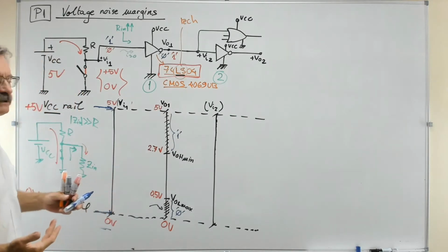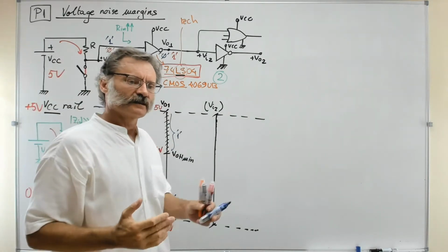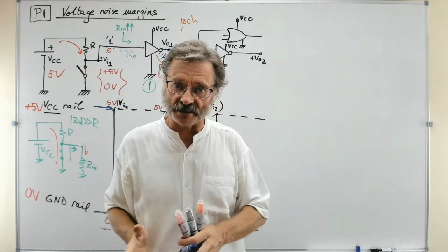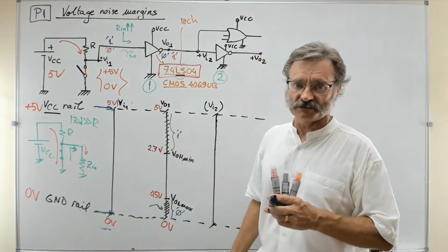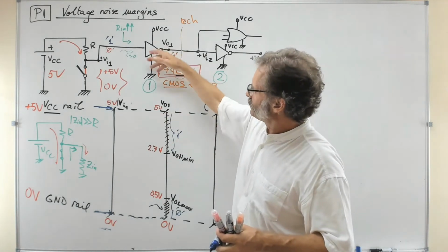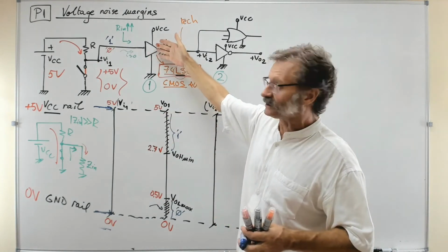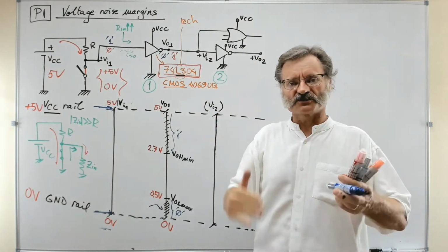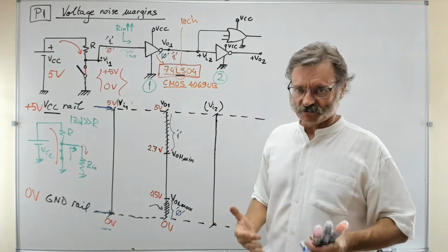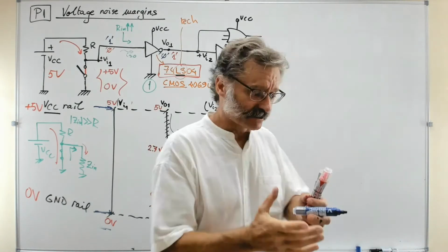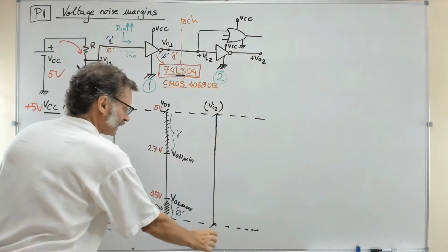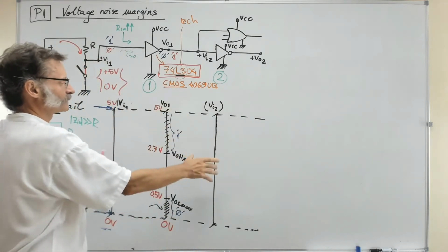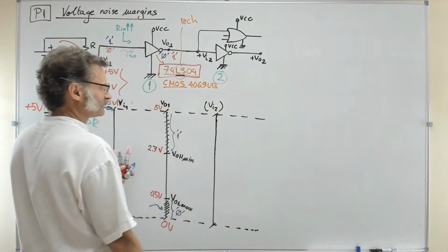So what is the meaning of this? That it has to be compatible. The circuits have to be of the same logic family, because they have to have compatibility. You cannot power this chip at 1.2 volts and the next at 24. That has no meaning. There's not going to be understanding here. So this compatibility is clear when you represent this second axis. You see, this is the axis or the line representing the voltage output. And this is the axis representing the input.